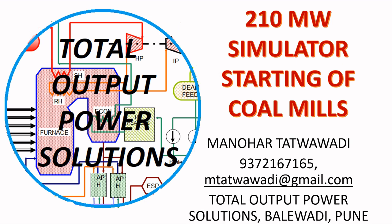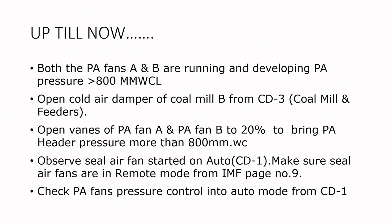So, till now, what we have done, we have started the PF. Both the PF fans A and B are running and developing a PF pressure. Now, we check whether the cold air damper we have opened or not. Check whether the cold air damper for coal mill B from CD3, we open the cold air damper a little bit. The gates must be open, the gates also should be open, cold air gates.